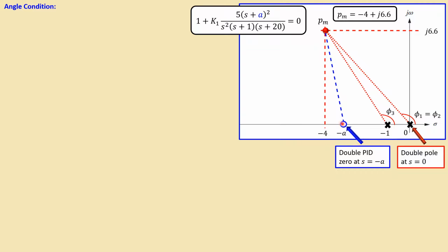If this is a value for the phase, so this phi A, if this is larger than 90 degrees, this location is correct. If it is between 90 and 0 degrees, it must be in the left hand side. We also know that we have -20, that's also fixed for our pole, which is due to the filter, and that will be then the phi 4. So we have now all the necessary phases and also the lines connecting to that design point.